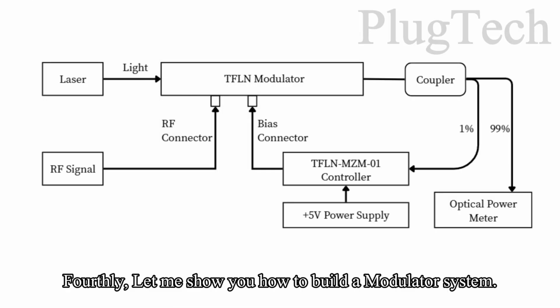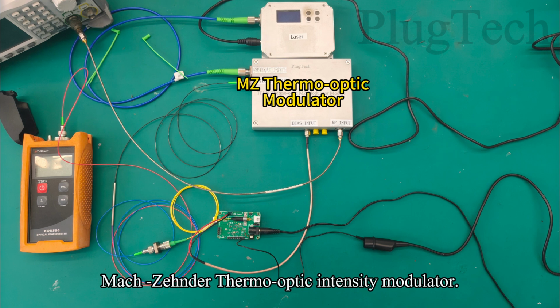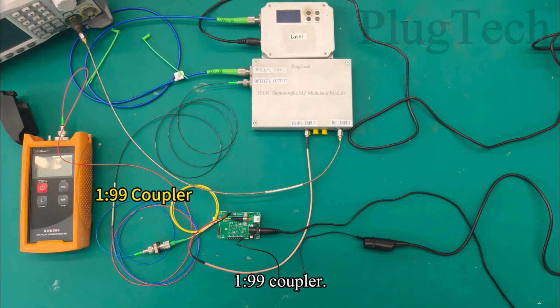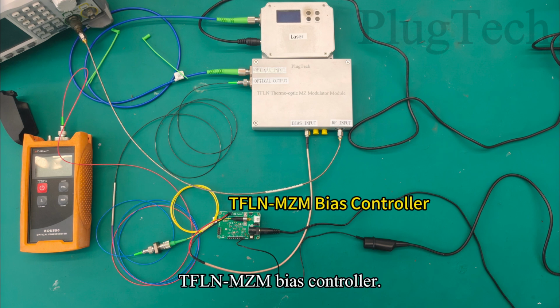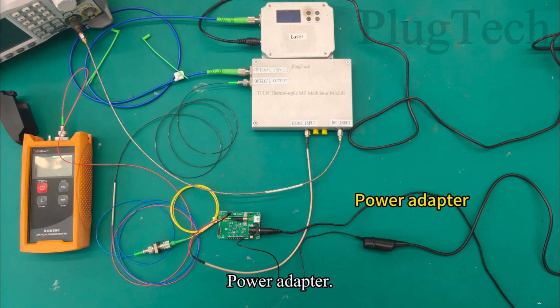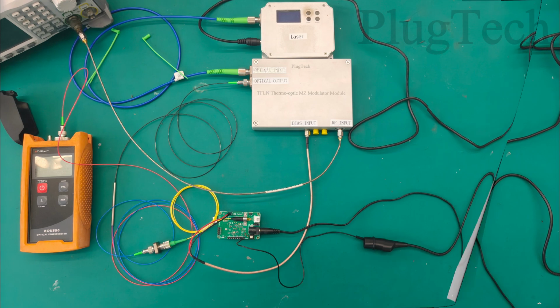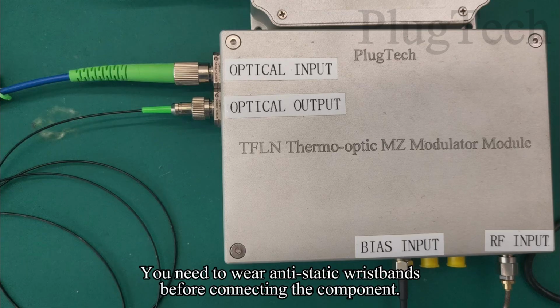Fourthly, let me show you how to build a modulator system. The system includes the following components: laser, Mach-Zehnder thermo-optic intensity modulator, 1:99 coupler, TFLN-MZM bias controller, signal generator, power adapter, optical power meter, ground wire. You need to wear anti-static wristbands before connecting the components.